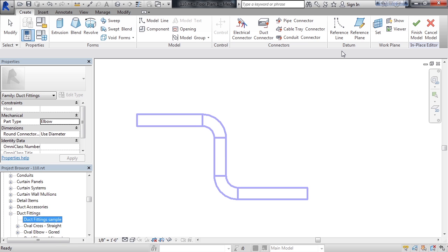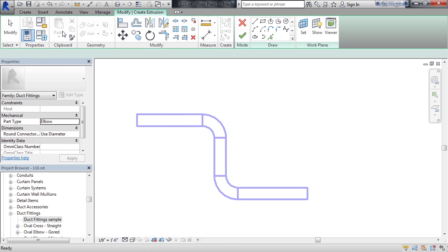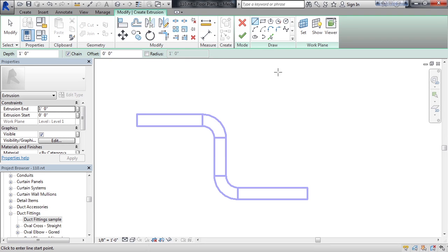An example of how to do this without going in depth, because creating family files can be a pretty elaborate task, especially if you're adding in a lot of the content, and we're not focusing on that just yet within this lesson. A quick example to show you this would be I want to create an extrusion, basically some three-dimensional geometry. I'll go to the Forms part of the ribbon. I'll click Extrusion. That will now change to the Drawing Edit mode, and over on the right, I'm going to select Basic Line. This will allow me to basically draw lines, similar to sketching. And then I'll use my existing geometry for the ductwork simply by starting to select different points and then drawing some rough geometry for the shape of this duct.